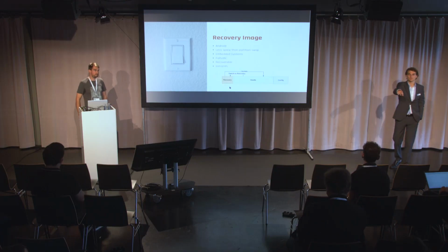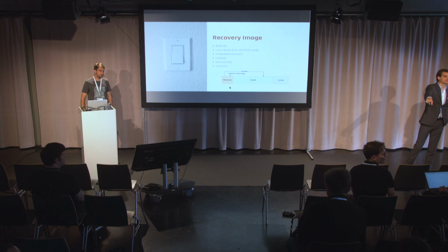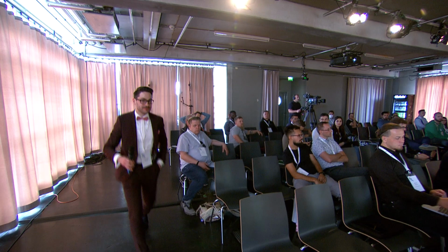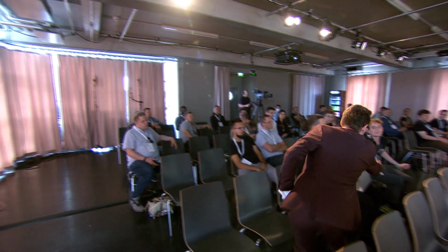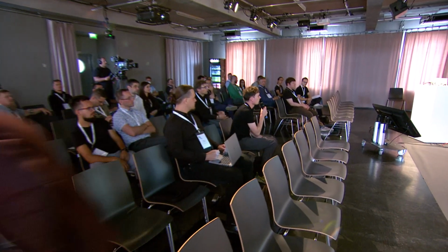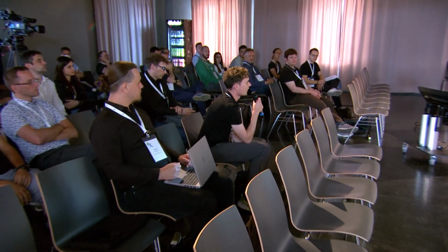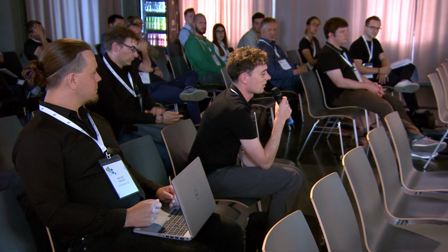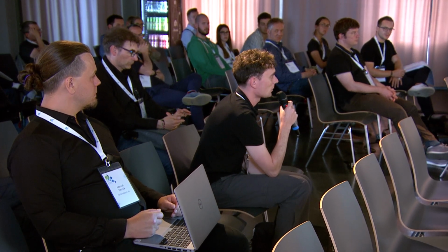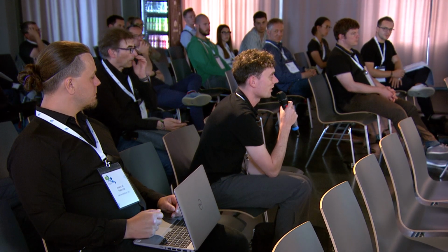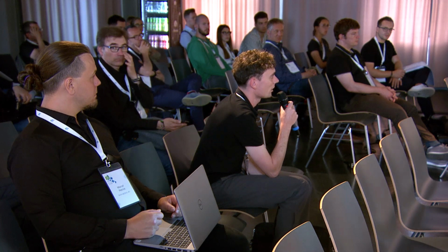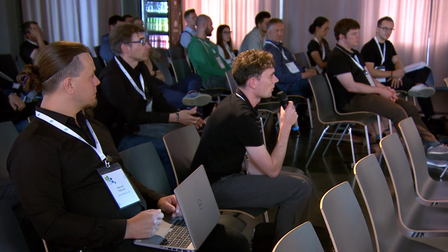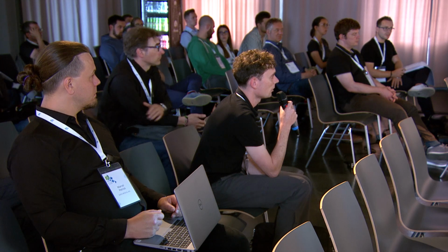There was one more question here in the front. I was wondering about the U-boot update. Sometimes, hopefully not a lot, you need to update U-boot and then it can't boot the old kernel, and the other way around. Are all the mechanisms provided by default?